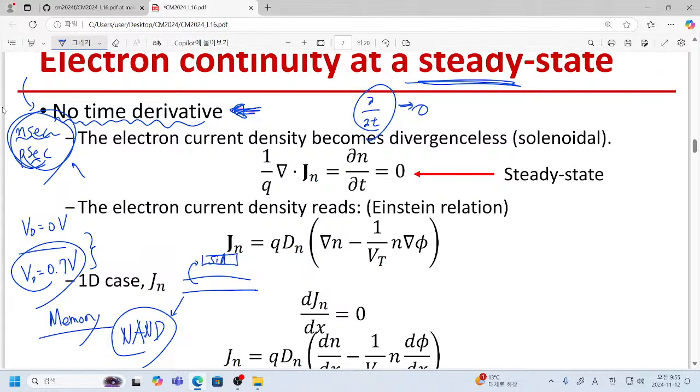Here we have a silicon nitride region, and the amount of electrons injected into it determines the threshold voltage of our NAND cell. The current density is so small that it takes quite a long time to have a meaningful difference of our physical or electrical quantity.